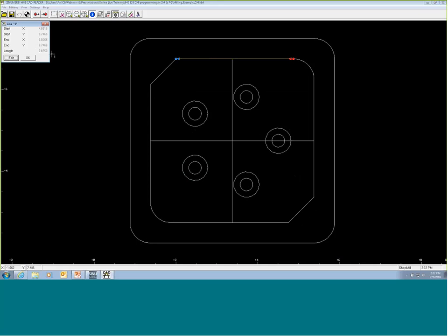So, first, if I start to look at these numbers, they start to look a little funny to me. The length makes sense, but my absolute positions seem a little strange. Same scenario if I was to look at holes, and I'm paying attention to where maybe the center line or center point of the hole is, it doesn't quite look right. So this would be where I would use the scale down in the lower left-hand corner and my cursor position to try to figure out where the part 0 is.